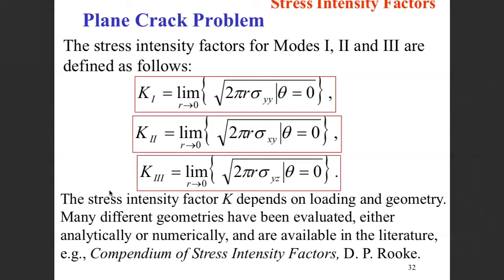And guess what? The actual stress intensity factors for the internal of a 60-degree V screw thread was in this book, right? Every possible geometry that you can think of, the stress intensity factors are there. And they're all worked out by basically this same procedure, right?